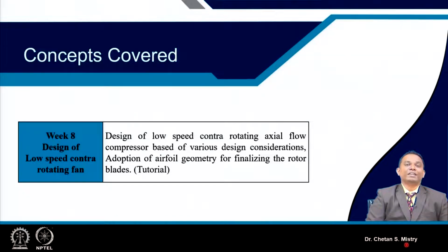What we realized is that when we opt for the free vortex concept, our blades are highly twisted, both for rotor 1 as well as for rotor 2. At the same time, with the fundamental design approach, where we have great control over parameters, we can make our blade less twisted, and that is expected to give a wider operating range. Secondly, manufacturing will be easier when we go with the fundamental design approach.